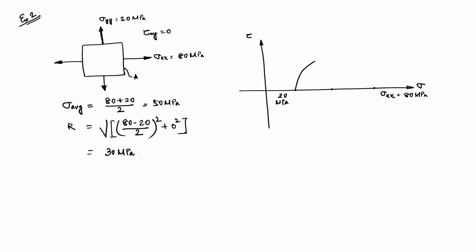If we draw the Mohr circle, we can find out what is the tau n, right. So, this is 30. The point to be noted here is that the plane A is actually the principal plane, and here you have the maximum value of the principal stress. Similarly, plane B, which is here, will have the minimum value of principal stress.